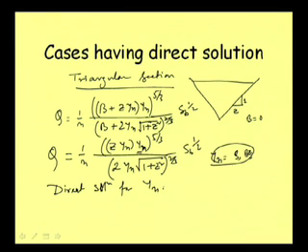Well, that means that although we have all the other different procedures that we just talked about, for a wide rectangular channel and for a triangular section we do not need to go for all those methods, and we can directly calculate the value of normal depth.